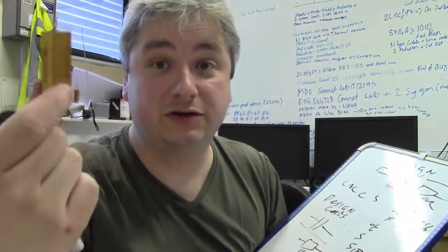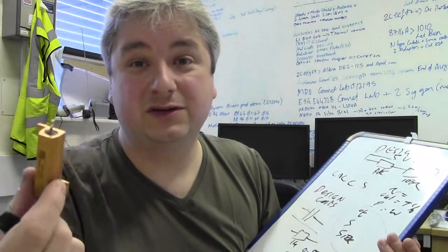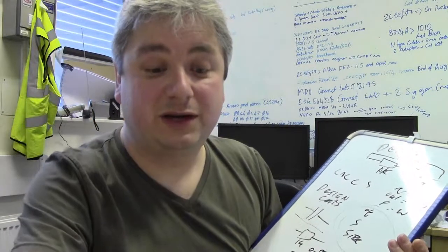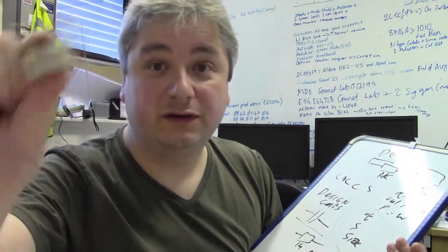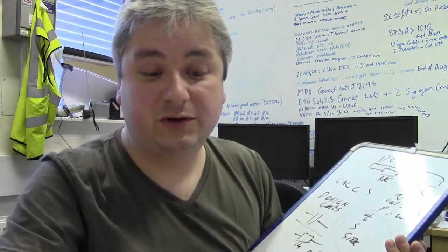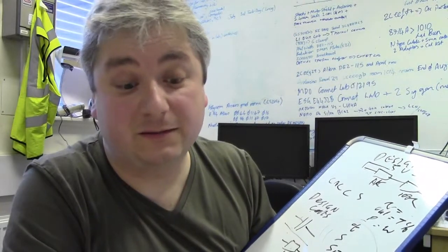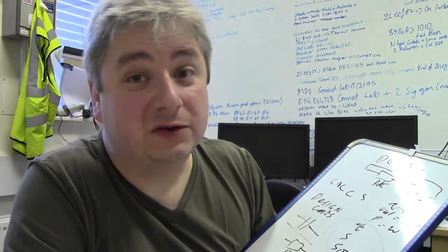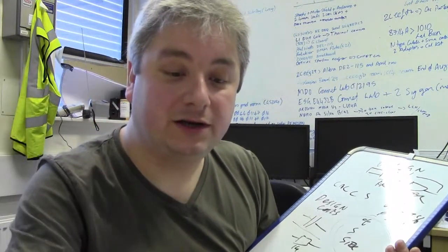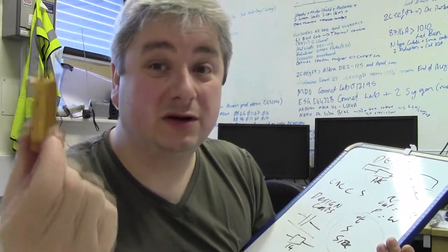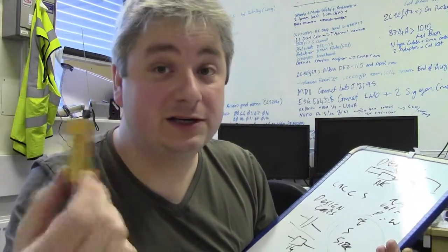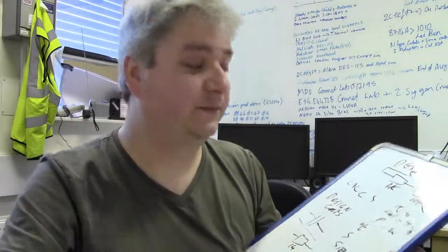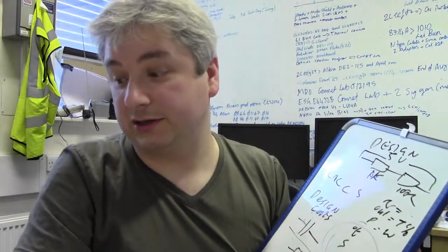So you might have to go for the huge chunky one, but your design constraint says that you can't, so you might have to dump the metal one and try and go for the ceramic type resistors. You may have to be very, very on the edge of your power rating, and you won't be able to overrate it, or you might be able to overrate it by whacking one of these in, and your design lasts a hell of a lot longer than it would do with one of these. It's all down to that design. So that's your design side of things.